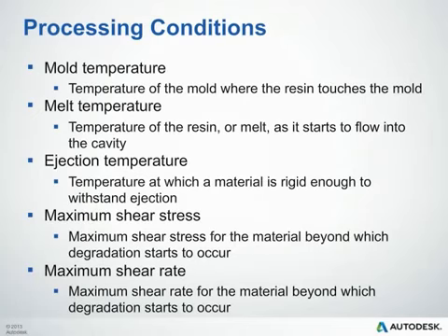The maximum shear rate is the shear rate at which the material will degrade as well. If we want to look at shear stress and shear rate, think of a polymer as flowing in many layers. It's in laminar flow. The shear stress is essentially the force being exerted between those layers.